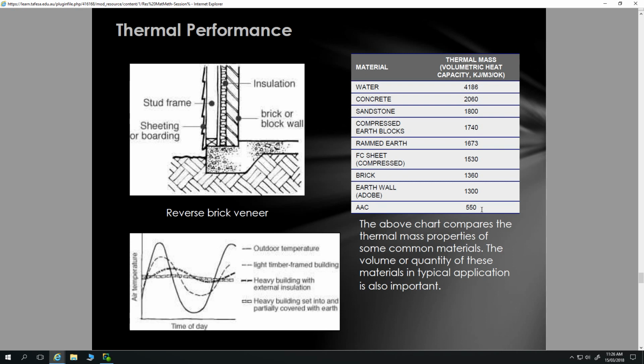I visited a rammed earth house once in the morning, and it was shocking because of the use of rammed earth for external walls on this building. Yes, rammed earth has a low embodied energy, so that's certainly a virtue, but it has very little insulation capacity, so it transmits heat really well.